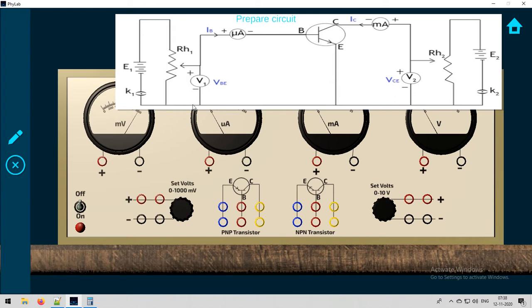On the left side and right side there are two black knobs. Those are the batteries. So consider those as the batteries with positive and negative terminals, and connect the remaining parts. The first thing is the negative terminal of the battery is connected to the emitter of the NPN transistor. So here, two batteries' negative terminals are connected to the NPN transistor. Click on the terminals where you want to connect, and the wire automatically gets connected for you.